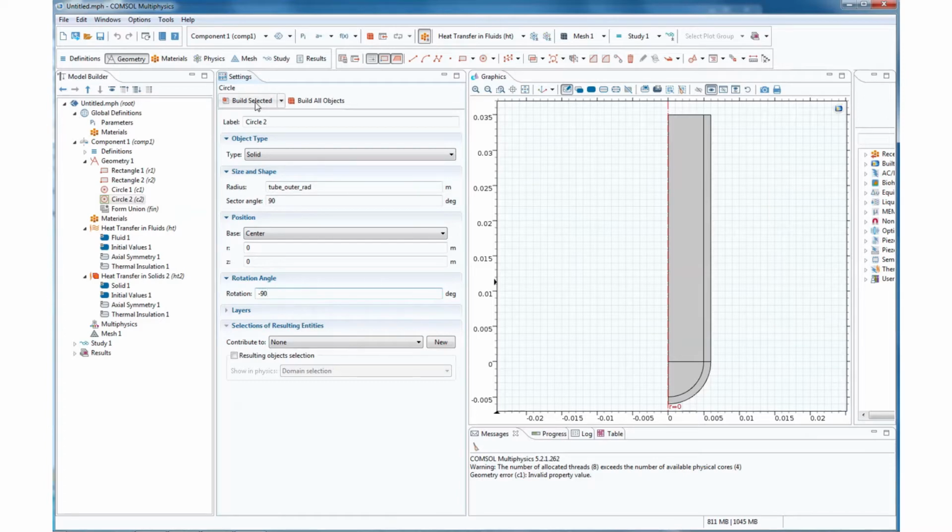So what I'm modeling is like the cryovial is just a tube. Since it's axisymmetric, everything's going to rotate around that red axis you see. So you only need to do it on one side.